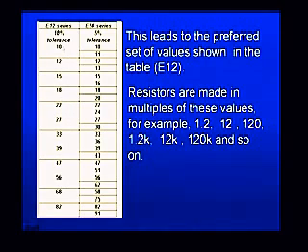For example, I can add another 0, so 100 ohms, 120 ohms, 150 ohms are also manufactured, 1000 ohms, 1200 ohms, 1500 ohms, etc. 10 kilo ohms, 12 kilo ohms, all values of resistors in different denominations will be manufactured, having values only as shown in this column of the table if they belong to 10% tolerance.